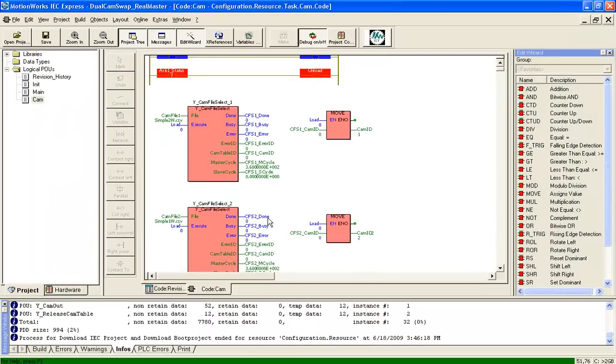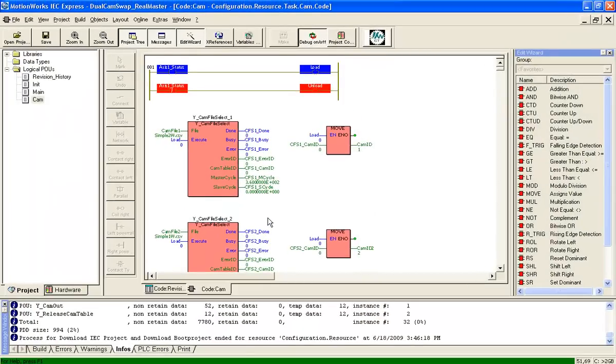So now we've demonstrated to you the basic features of how to select cam files that have been preloaded as CSV files, and these can be created either by Yaskawa's CAM tool, or they can be created by an Excel spreadsheet and then transferred to the control. We've shown how to do a simple cam scale function, a cam shift function, and a slave offset function, and we've shown how to simply adjust cam files on the fly.